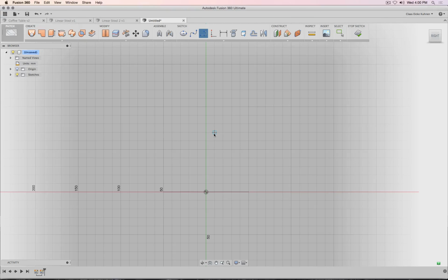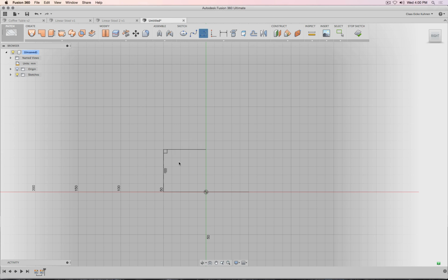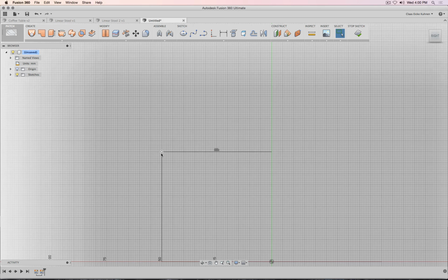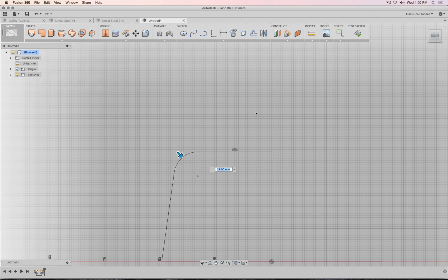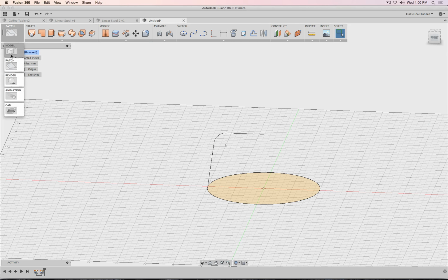And let's take a look at the revolve solid command first. The way this one works is I can start with a line. And where is 50 actually? There's 50, okay. Click and click. Delete those constraints. This one we can actually maintain horizontal. Okay, maybe move this one over a little bit. And if we want, we could fillet the sketch. Okay. And then let's go to model.